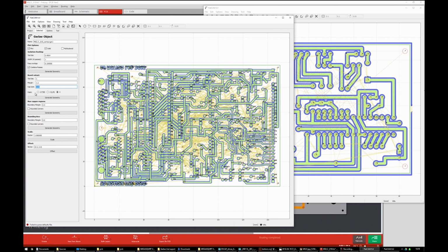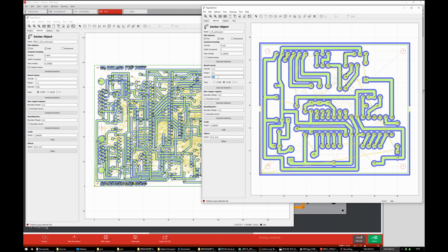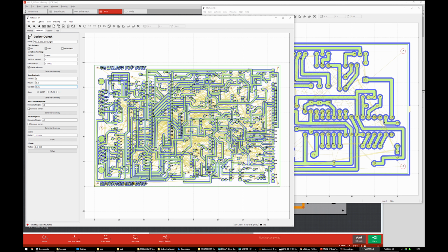But this means there's a bit more manual work actually popping out these things when they're finished. But what I usually do for a single design, the least amount of work post CNC, is to do 2 tabs, top or bottom or left or right. I don't know. Let's do top and bottom because that's the larger side. Gap size. Do you know what? PCBs are quite strong, and I used 2 here. I could probably even go smaller for this, because I'm only going to cut one of these.